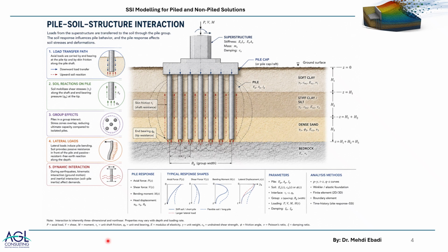But for a piled foundation, even assuming that it's under pure vertical load, the load that is applied from the superstructure is transferred to the top of the piles, and then from the piles to the soil, depending on the design and resistance provided by the side resistance or the tip resistance, or both, on this pile.